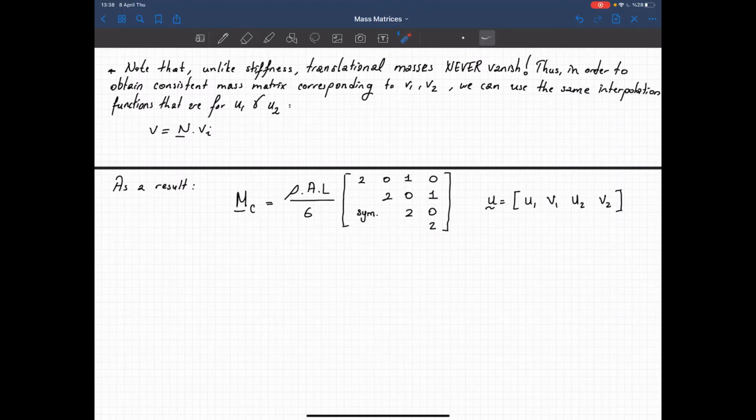Now we can generate a consistent matrix in the following way, but when you look at this matrix, you see that it's almost a full matrix. And in the integration algorithms that we calculated, if we have a diagonal form of the mass matrix, then we can perform numerical integration in a more computationally efficient way.